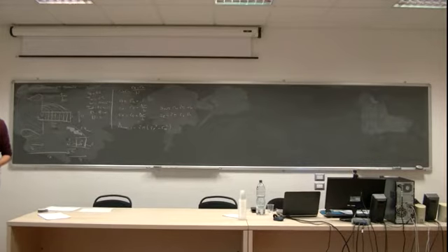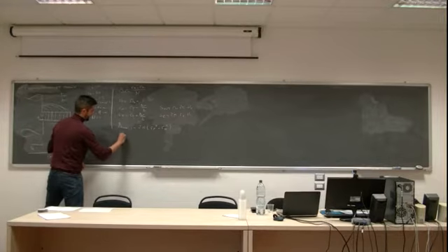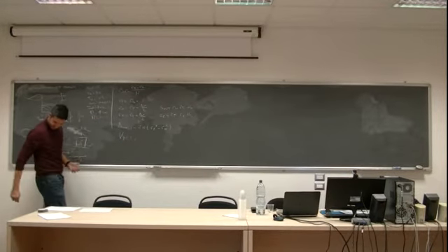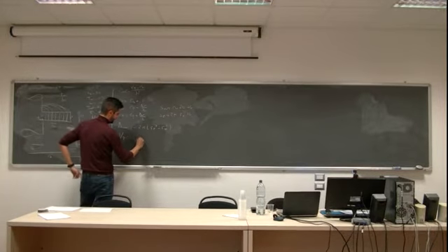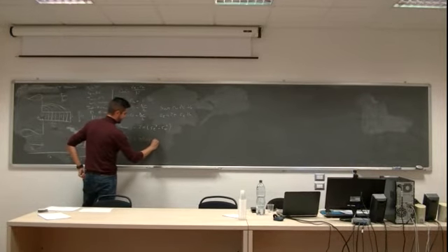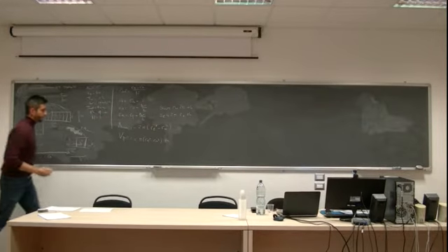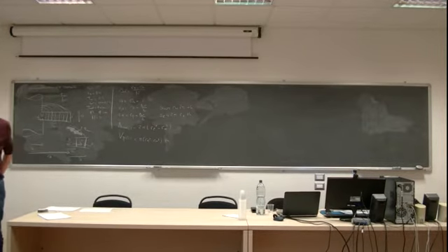For steady state problems, I don't care about volume. But for transient, I do need to care about volume, because the more mass you have in a node, the more energy you can store in that node. Right? So, if I need to compute that, each node has its own volume.